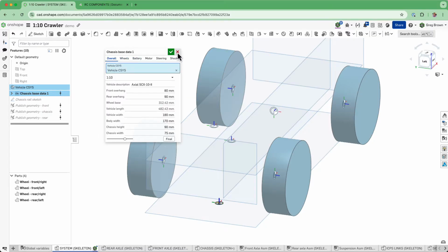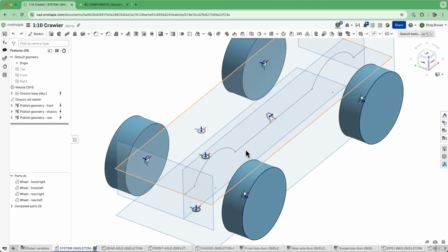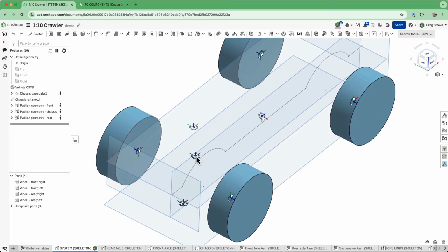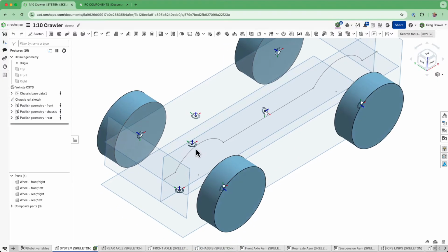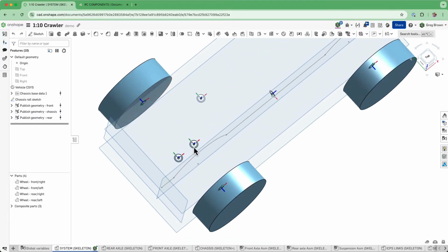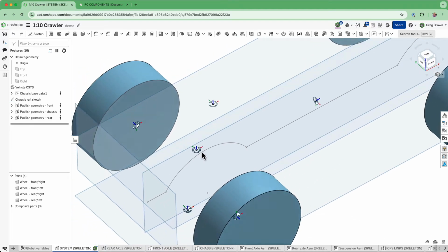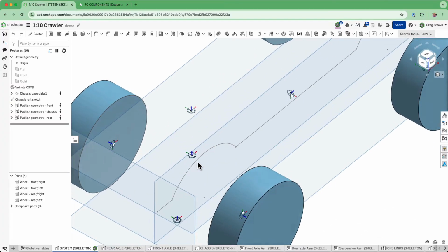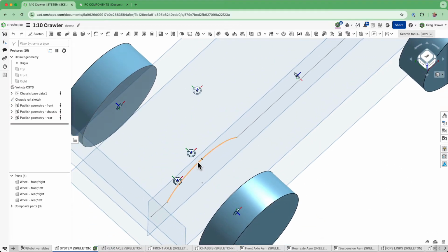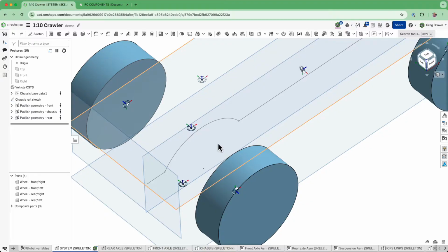So let's not dwell any further on that, because let's focus on, now that we've got these positions and specific, now I use mate connectors as a really, really powerful way to provide these hard points. A mate connector, as you know, is a multi-purpose powerhouse, let's say. It is a point, it is an axis, it's a plane, and it's a coordinate system, all in one, right? And it's a really, really convenient way to capture all of that with the minimum amount of construction geometry.